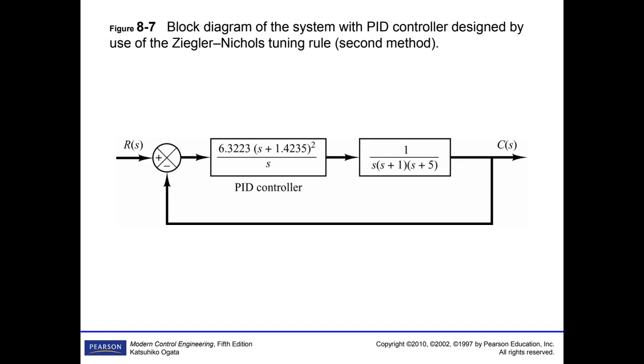You should now combine the knowledge you have from circuits and from signals and systems. It's going to open up your mind. What the S domain actually is: S has a real component and an imaginary component. But for Bode plot, we assume that your input signal is sinusoidal. Therefore, you are not going to take any real part into account.